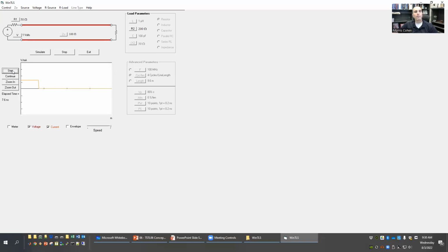So here they go, right? When this reaches the end of the transmission line, we're going to get a positive reflection coefficient for the voltage, but a negative reflection coefficient for the current. Why? Because the water level, which is basically voltage, builds on top, right? We got 1 volt coming in, we got a reflection of 1/2, and that builds on top. And so in total, we get the sum of those. The current works in the other way. If I've got water flowing this way, and I've got water flowing the other way, those two flows cancel each other out in terms of like the net flow of water.